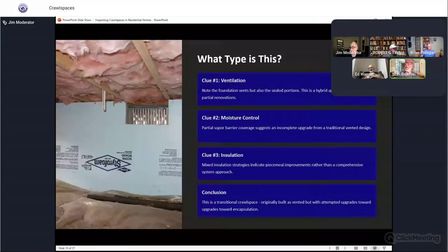Again, if I see that there's a major sag in the kitchen and that's right above the column, then we have a problem. So I go case by case. And don't forget, a two-story building, which we have here over the crawlspace, has much more weight on it than a ranch style, a one floor. So you've got a lot of things to take into consideration. It's something that should be called out for evaluation, but not necessarily as an emergency. If you have a 300-year-old house, it is sort of what it is.